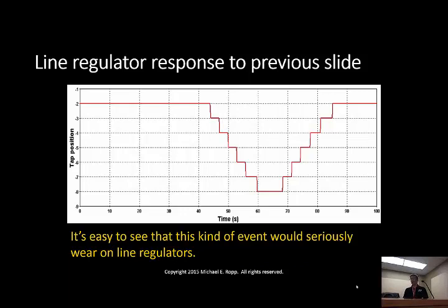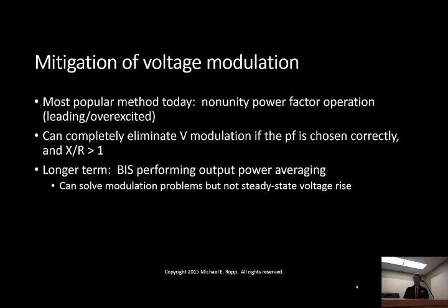If you don't have that going on, though, the regulator is going to try to catch up with it, and then you're going to see something that looks like this. This is a fairly fast regulator. You can see that the change interval is real short on this one, but it's a standard 0.5% per tap regulator. And as we mentioned before, there were several 0.5% in the voltage difference. So the regulator starts banging away to come down, try to catch this, and then it starts banging back up. That's going to wear the regulator out fairly quickly.